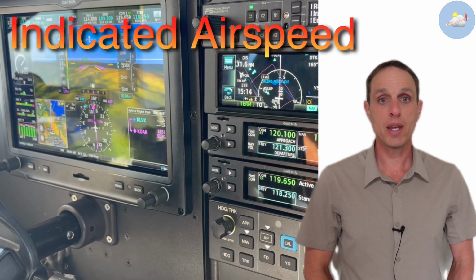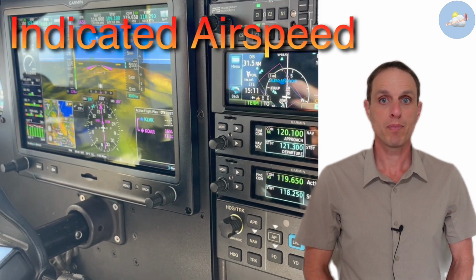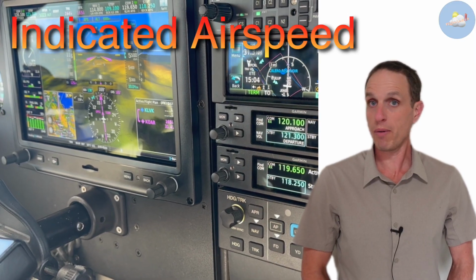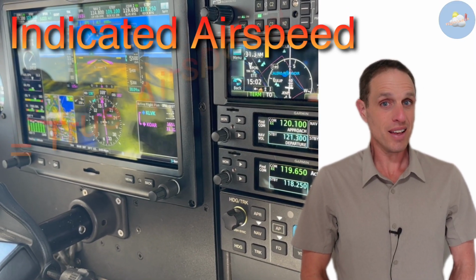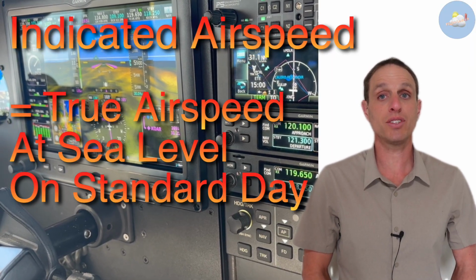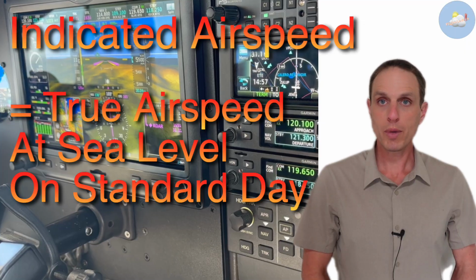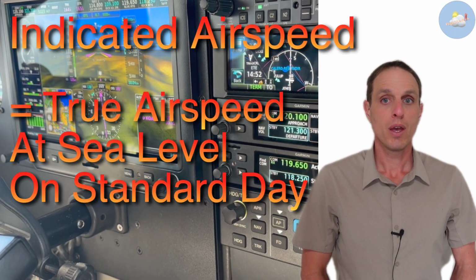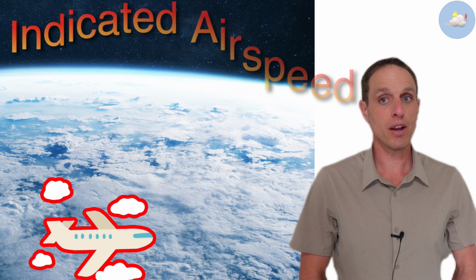The last key speed is indicated airspeed. You'd think your airspeed indicator would show your true speed, right? Well, it does, but only at the specific density of air at sea level. The problem is air density changes with altitude and temperature. That's why your airspeed indicator is only accurate at one specific air density. The higher you climb, the less dense the air gets.